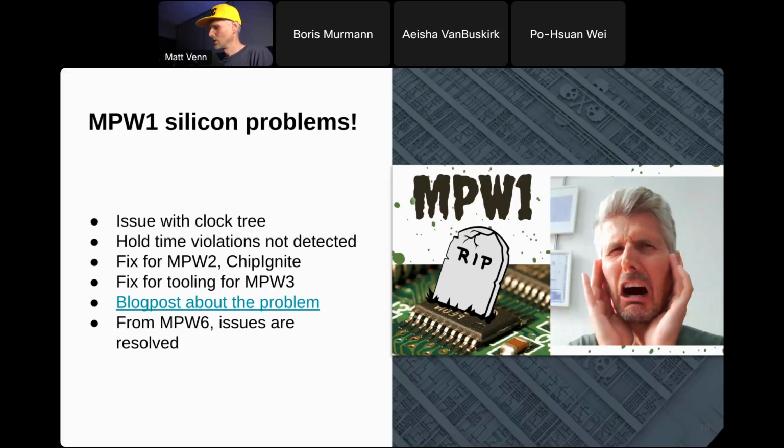Here's one here. My screen is quite small, but I'll show you some pictures later on in the slides. If you want bare dies, that's usually more difficult, and then you do also need the more expensive equipment. You need a wafer prober, or you need to do wire bonding. And then yeah, I see the Q&A section now.